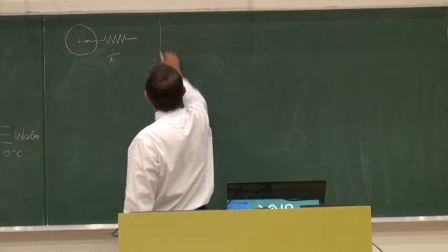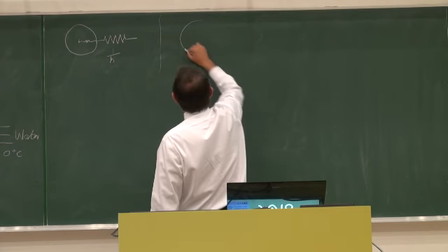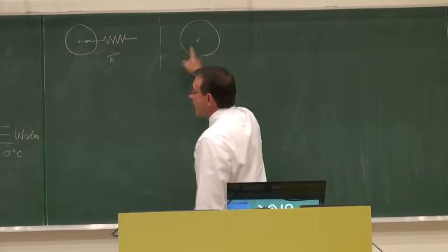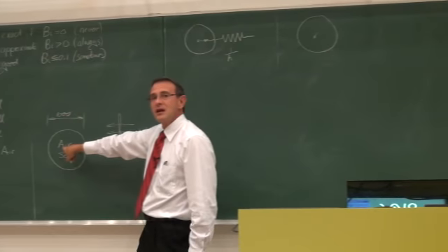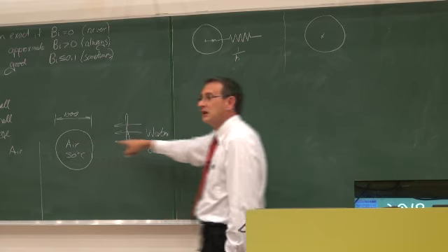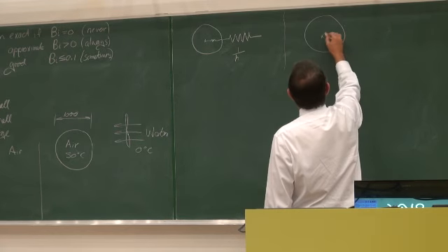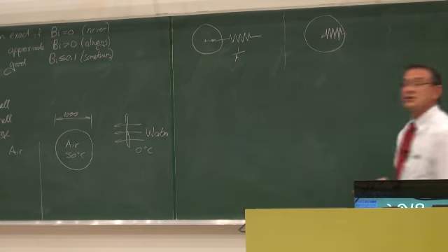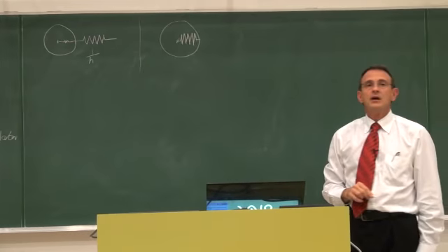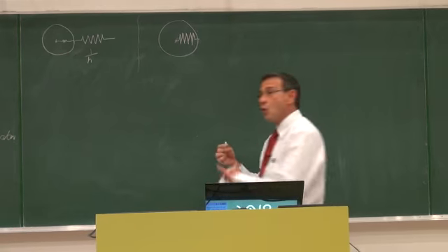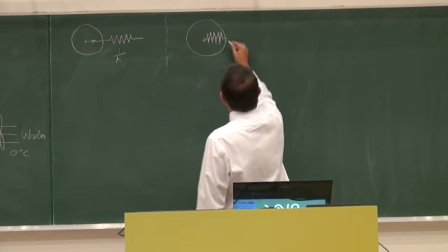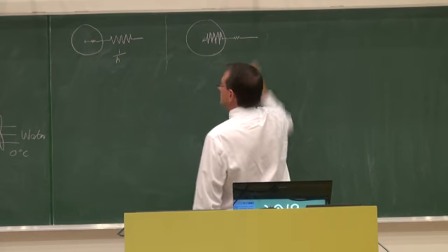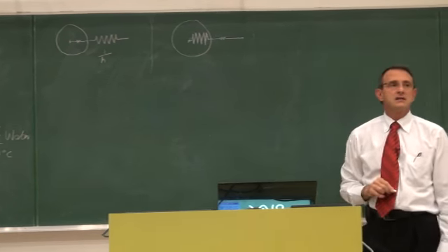So that is the one scenario in comparison with this ball, where we now have air on the inside. Now air has a very low thermal conductivity. Because the thermal conductivity is very low, we've got a very, very high resistance on the inside of the body, while on the outside we've got water which is being pumped over this air ball, and its resistance is very, very small. So two different cases.